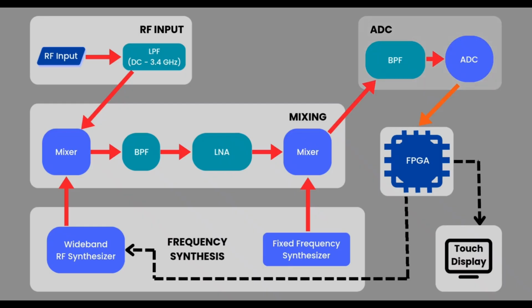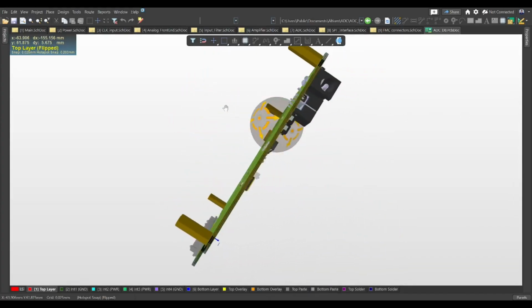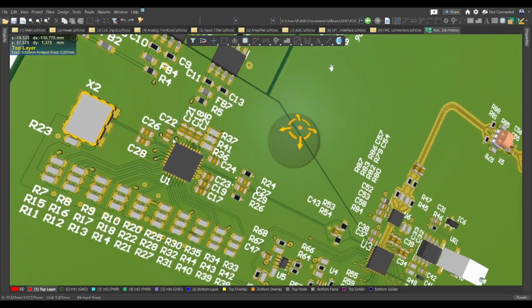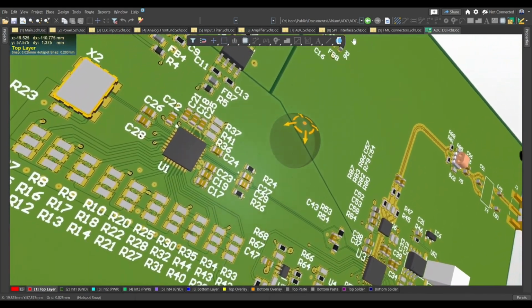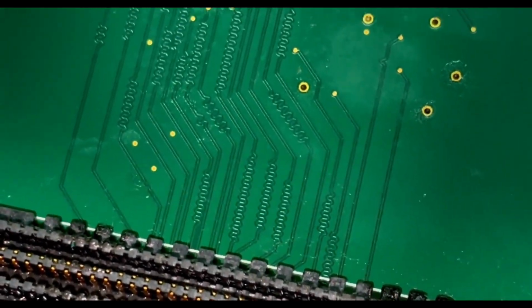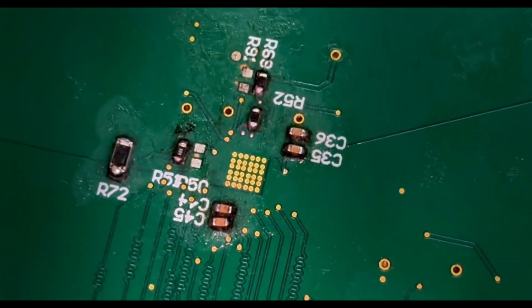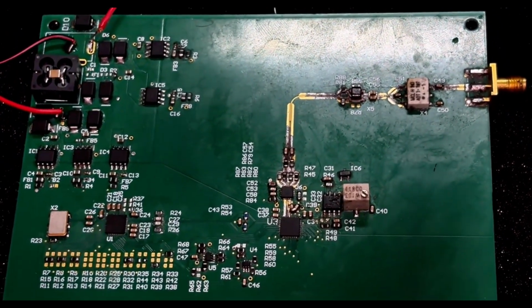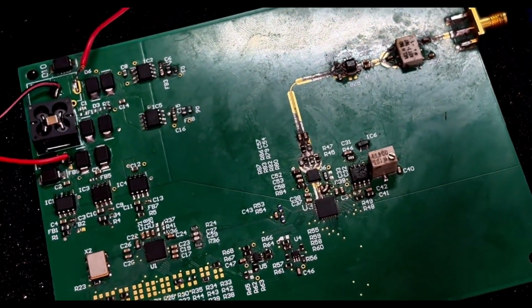frequencies. The filtered output is then digitized by a 14-bit ADC sampling at 80 megasamples per second, enabling real-time FPGA processing. The FPGA computes the RMS amplitude and maps it to frequency values. The ADC PCB presents key design challenges, including high-speed differential routing, precise impedance matching, and integration via an FMC connector to the FPGA.